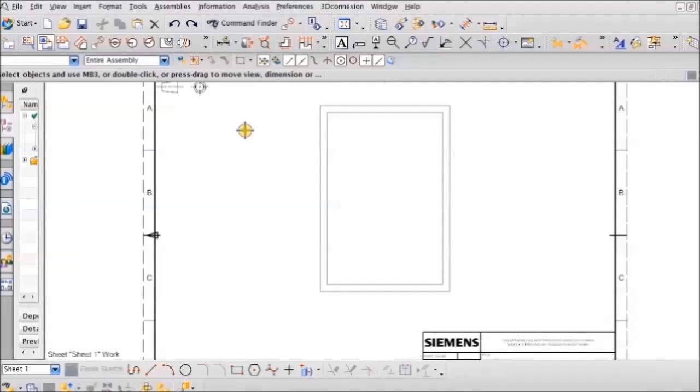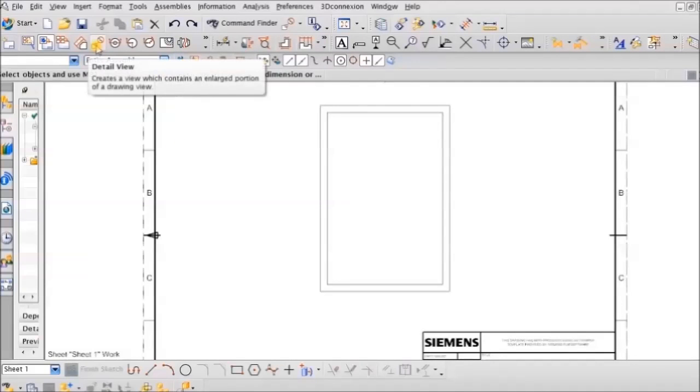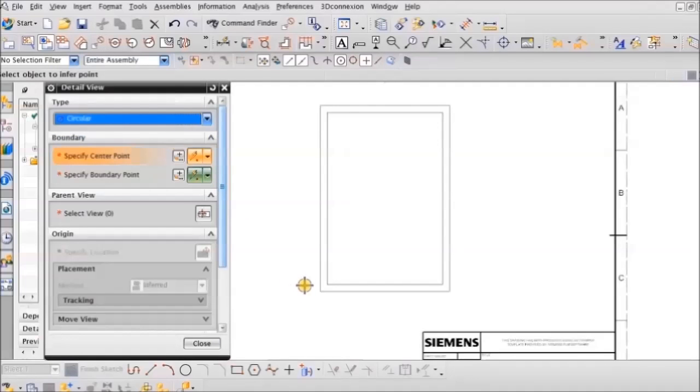And the last tip, tip number 6. Over here I would show you how you should actually position the drafting features. It concerns features like detailed views, section lines, or the view breaks. For example, if you create a detailed view, you shouldn't position it like this because the control point is not connected with the model.